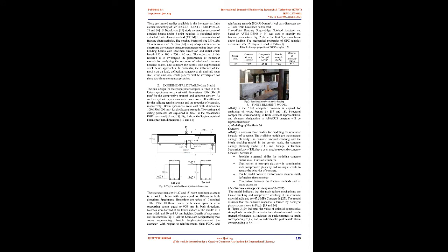Fiber geopolymer concrete, FGPC, is a type of eco-friendly concrete that may reduce the emission of a lot of carbon dioxide, CO2, in the atmosphere and thus represents an alternative to the cement concrete, CC, matrix. Its proven durability, mechanical and thermal properties are attractive features of GPC. Fiber reinforced composites are used to improve flexural strength and fracture toughness. Fiber reinforced composite materials have been playing an important role in the rehabilitation and repair of damaged concrete and masonry structures, due to their high strength-to-weight ratio, corrosion resistance, and ease of application.